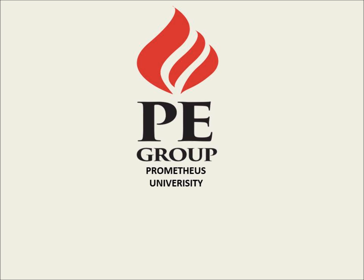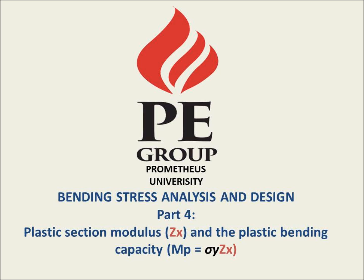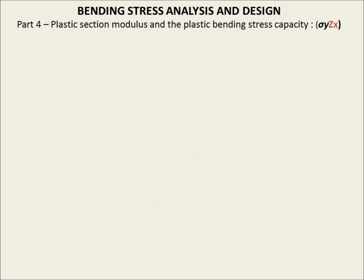This is the fourth part in our series on bending stress analysis and design. In this part, we'll be talking about the plastic section modulus, usually denoted as ZX. This video is a direct descendant of our first video, so I would advise you to watch the first video on the elastic section modulus, which describes the distribution of bending stresses in a cross-section while we're in the elastic phase. In this part, we'll be talking about the plastic section modulus, which describes the distribution of bending stresses in the plastic or post-elastic phase after the yielding of the material.